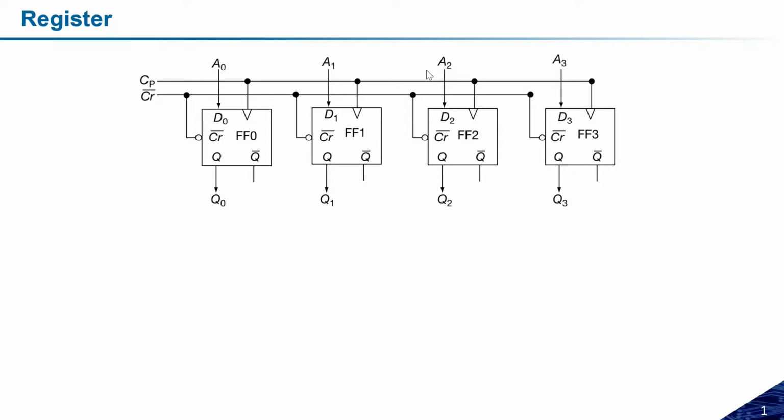Similarly, because the T flip-flop and the D flip-flop work on a toggling state. I made a mistake. JK flip-flop and the T flip-flop are based on the toggling states. They have some toggling kind of thing. Instead of an indeterminate state, they give toggle states. If they are giving toggle states, it means they can be utilized to count the pulses, how many pulses we have received by the flip-flop.